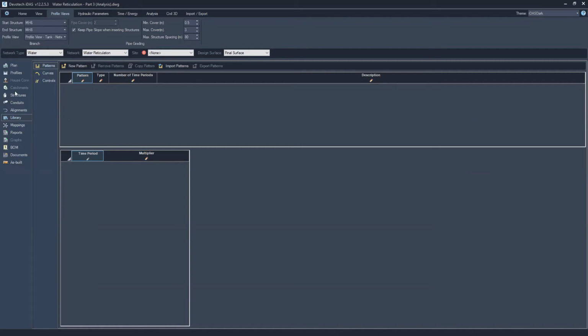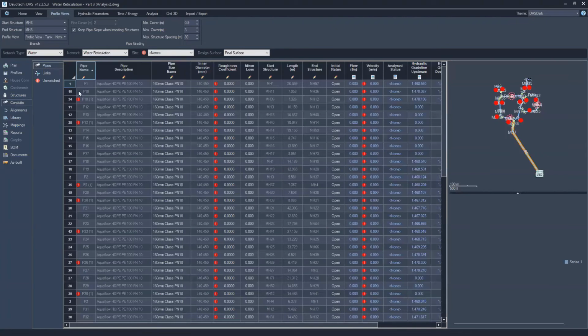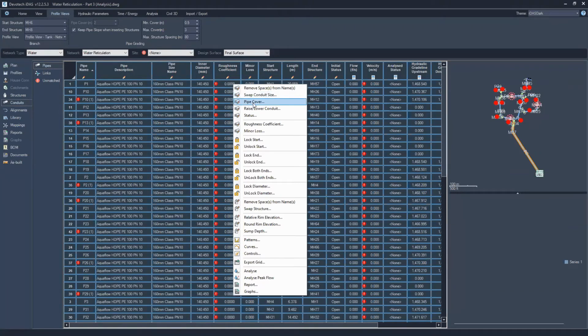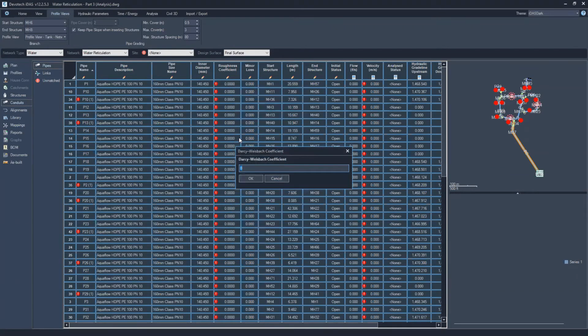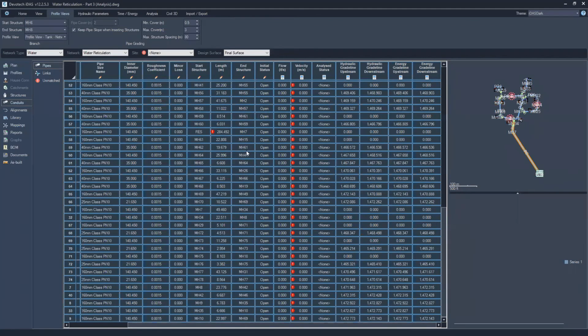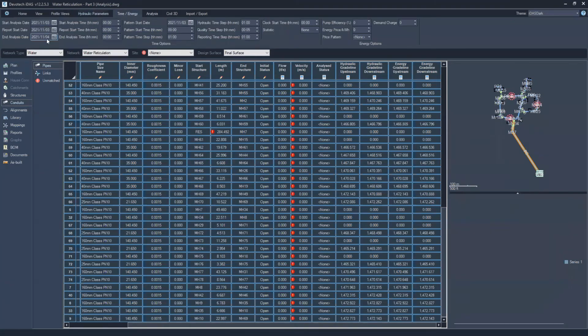All right. So I believe I just need to add the roughness coefficient to my pipes. It's HDPE. It just indicates that one of these pipes is too long. It's at 284 meters. That is this initial one. So you can go and add some nodes along there, provide some vertical bends just to reduce the length of the pipes there. All right. Hydraulic parameters, let's stick to this.